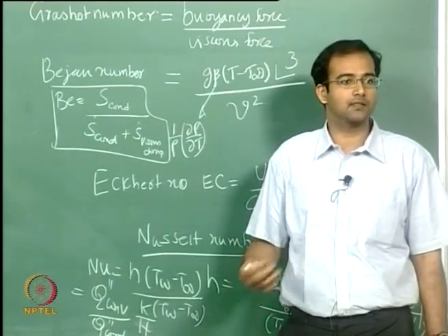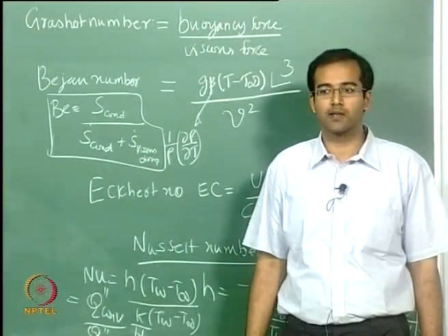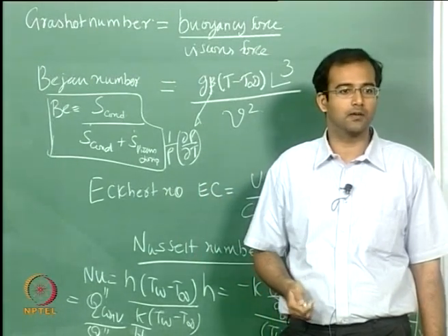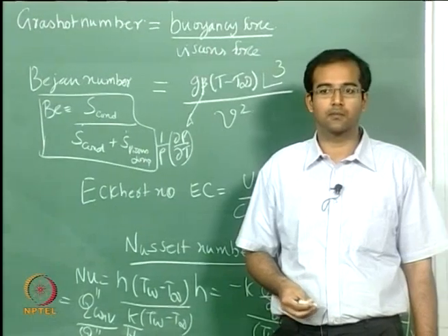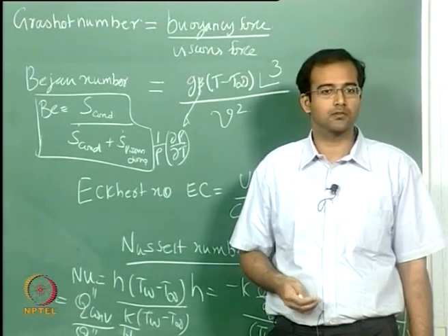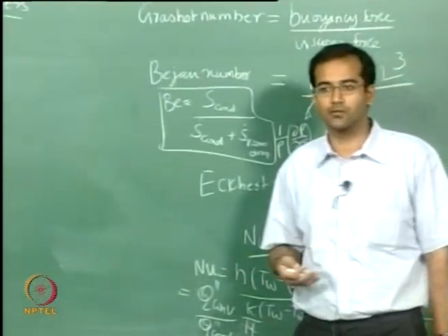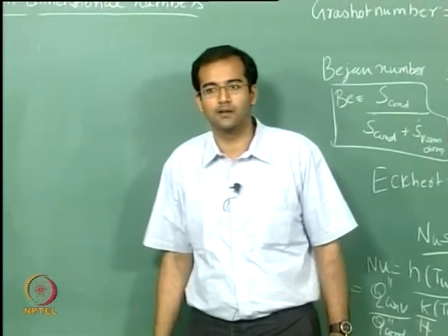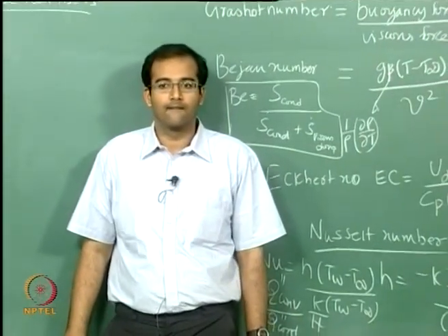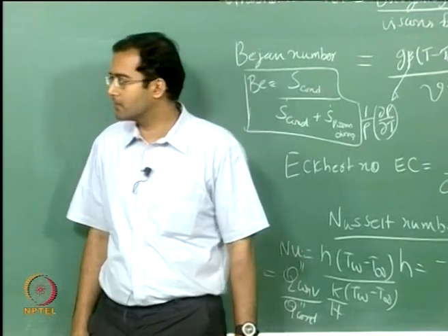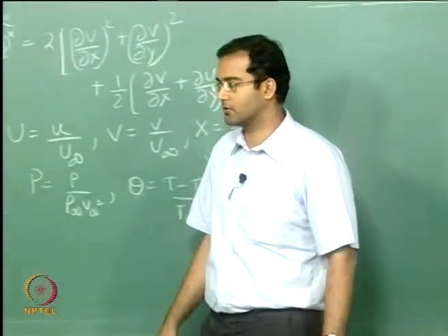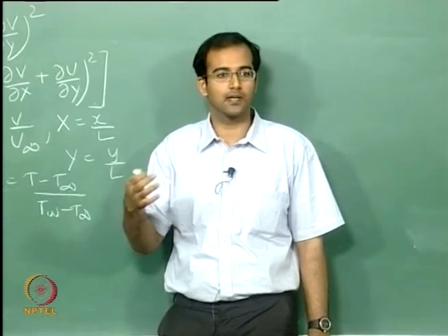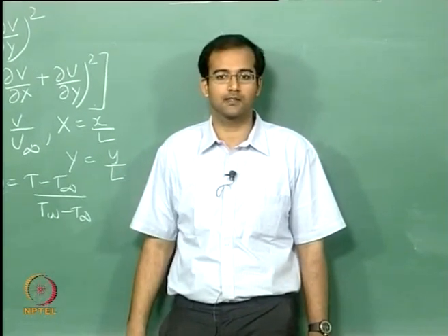If you go to multi-phase heat transfer, say boiling, then you will have other non-dimensional numbers: Bond number, Eötvös number, capillary number, and Weber number, and so on, depending on the forces that you encounter. Any questions on this? The Richardson number is, as I said, if you group your Grashof number by Re square and group them together as another non-dimensional number, that is called the Richardson number.